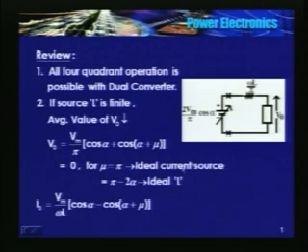It is also 0 for mu equal to pi minus 2 alpha, and we found that this is the case when the load is an ideal inductor. Now the value of I0 is given by this equation, Vm by omega L into cos alpha minus cos alpha plus mu. These expressions we derived yesterday.